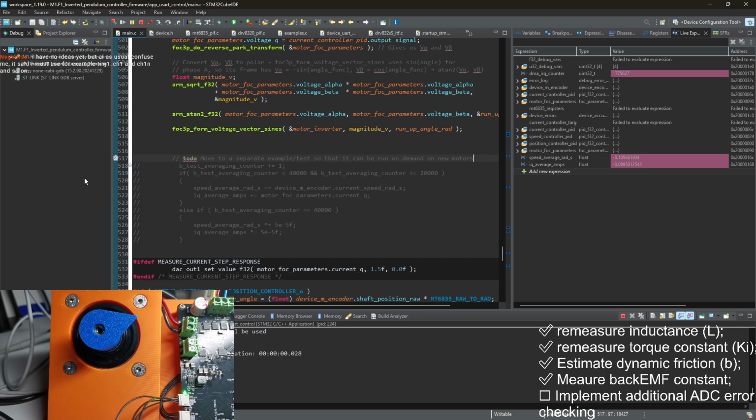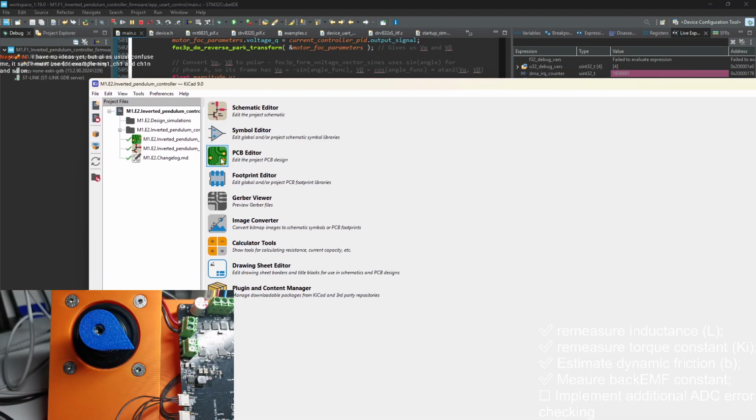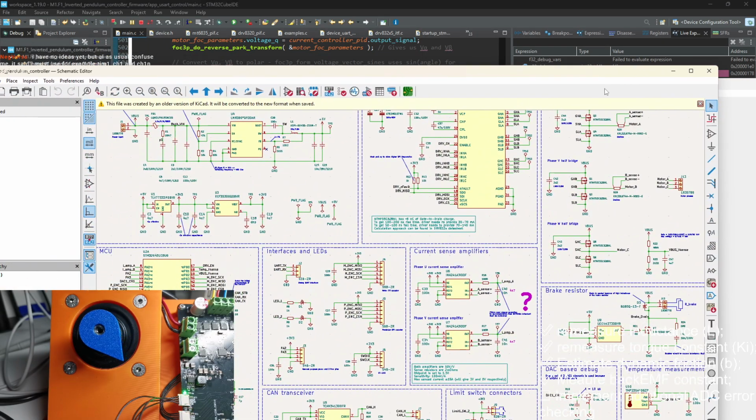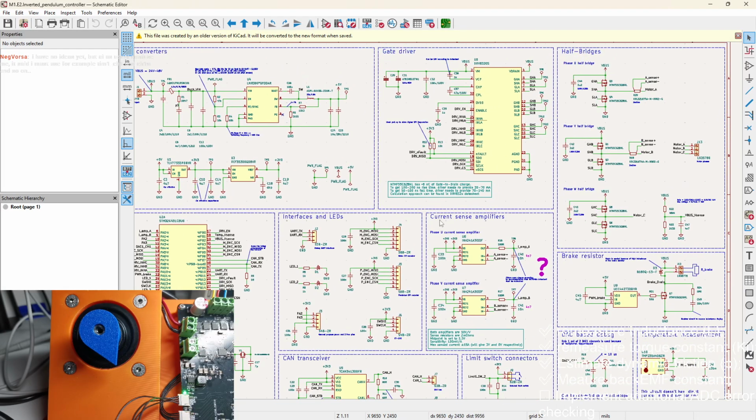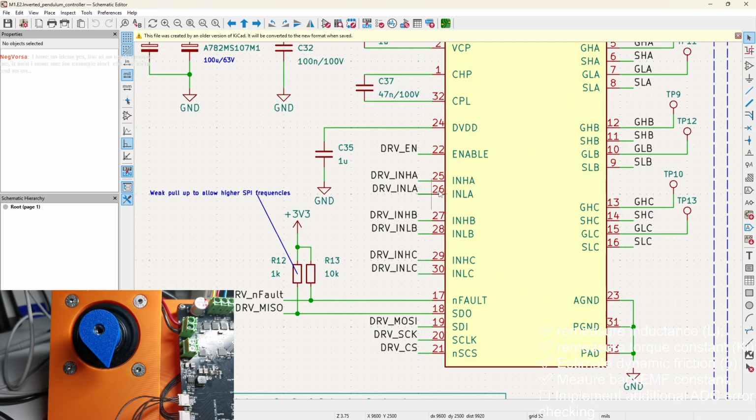Yes, you will need to use this if you want to provide 6 PWMs. I personally work with 3, so let me show you. Here, I only provide the high sides as PWM signals, which are all timer 1, channels 1, 2, and 3.